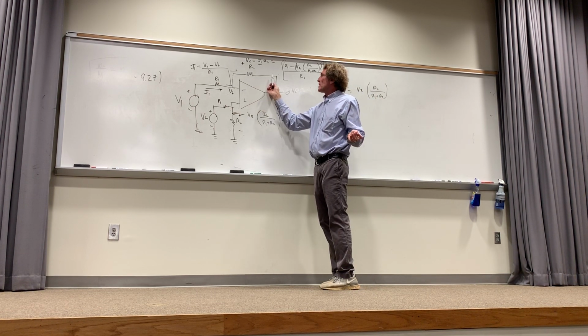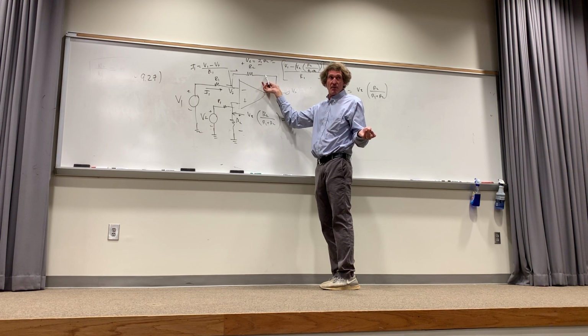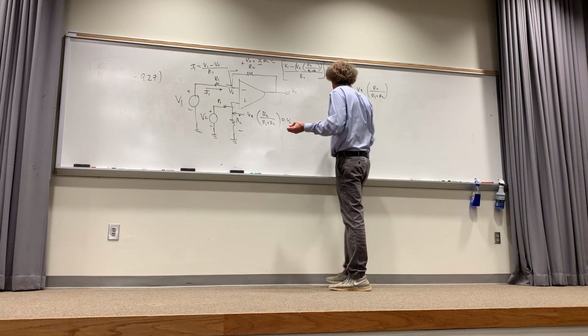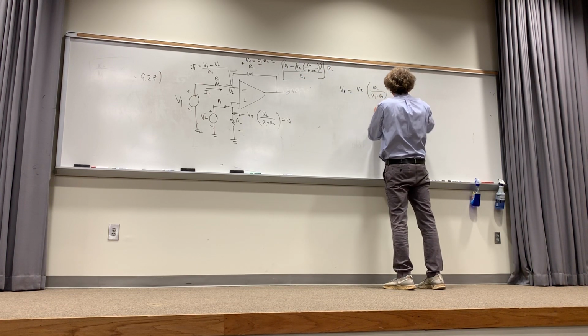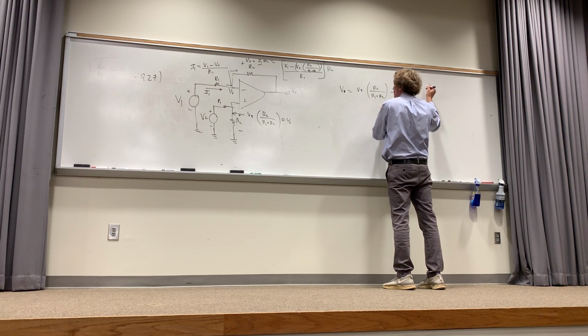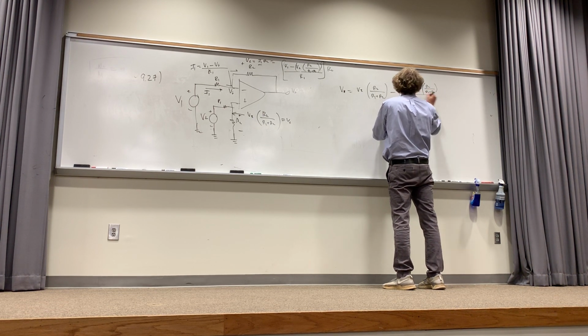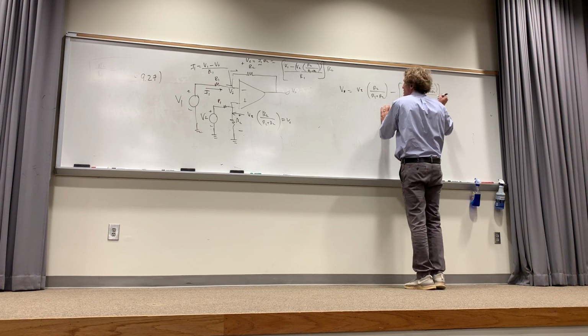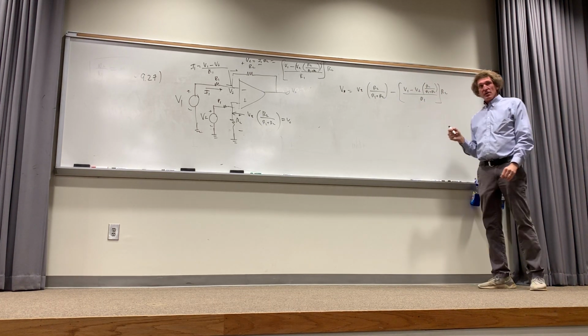And then from here to here, what do I have? Well, it's a drop, isn't it, class? Y'all follow me? That's positive, that's minus, so it's minus that voltage. That's that voltage, which is kind of messy, but it's V1 minus V2 times the quantity R2 over R1 plus R2. And then it's divided by R1 times R2. And that's V out. Y'all follow me?